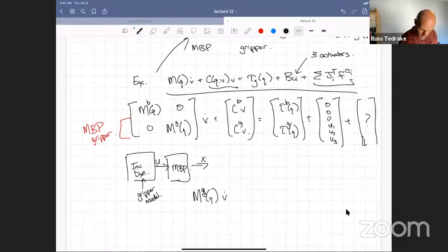my equations are CG. Alex wants to know what the C matrix is. Good. So this together is my mass times acceleration. When you get into multi-body equations, you have some terms from the Coriolis terms and the like, which is why we call it C, and the mass, but they go together to make up mass times acceleration on this side. And then this side I think of as being all the forces. So this is F equals ma.